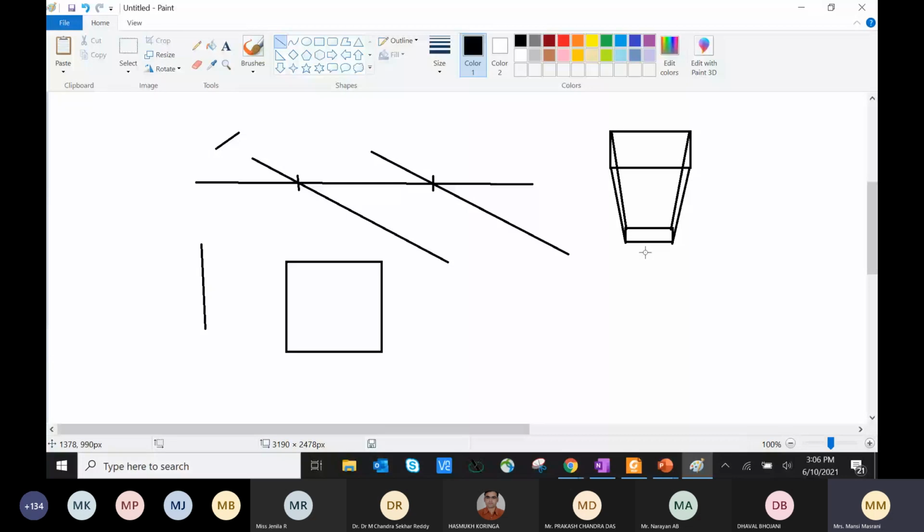But what happens if the vias in the design are few in number and your current is so high that the via wears out? When it wears out, it starts decaying from here, and it becomes half of it, or just a smaller part of it. From there also the current is still going through, which is very high in density, and then your whole via will wear out at a certain point of time.